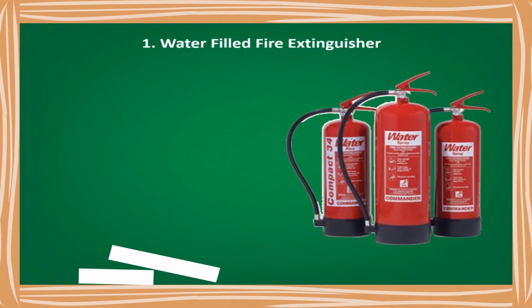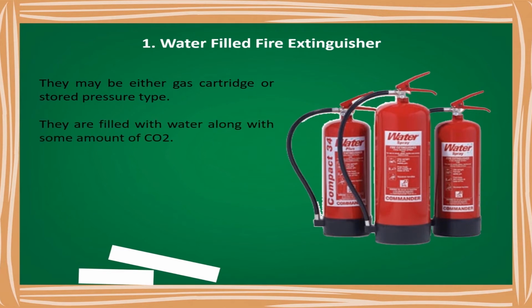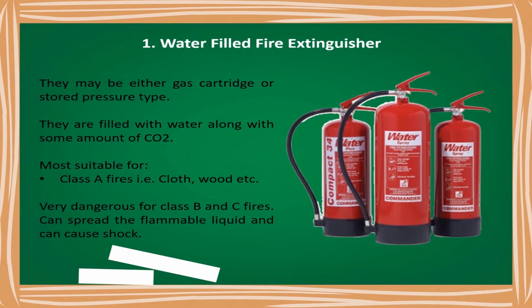Water-filled fire extinguisher. They may be either gas cartridge or stored pressure type. They are filled with water along with some amount of CO2. Most suitable for Class A fires, that is, cloth, wood, etc. Very dangerous for Class B and C fires. Can spread the flammable liquid and can cause shock.